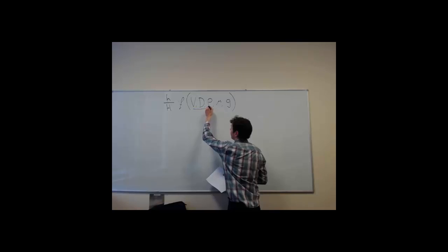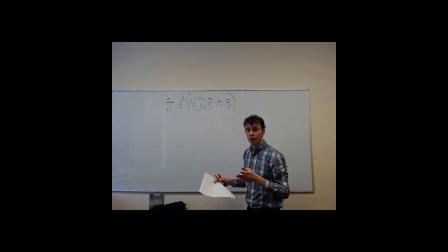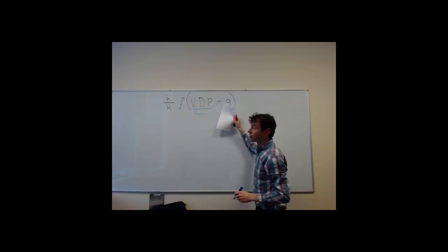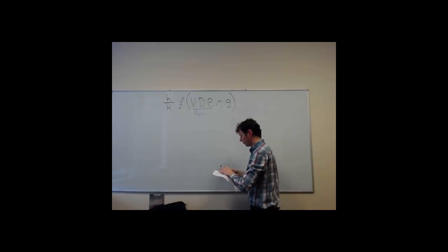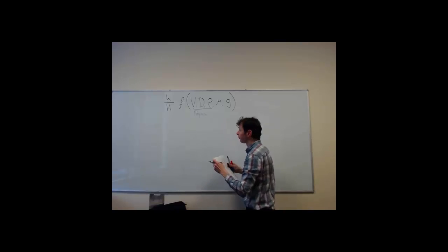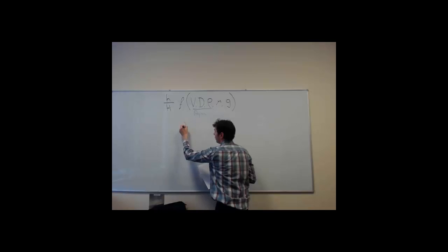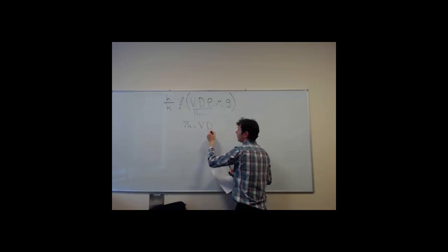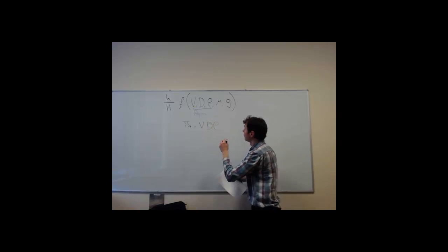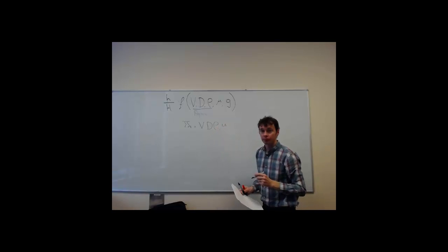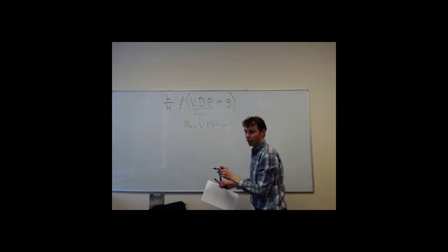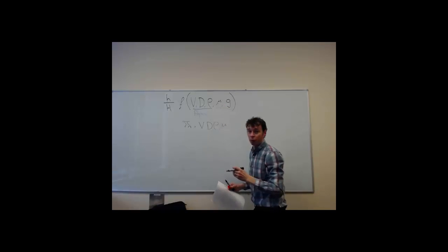So what we're going to do is velocity, diameter, and density, nice and easy to measure. They're going to repeat, which means that the dynamic viscosity and acceleration due to gravity are going to appear in one group each. Okay? So for our first pi group, pi 1 is going to be equal to velocity, diameter, density, and dynamic viscosity. The second pi group will be v, d, rho, and then acceleration due to gravity. So these variables only appear in one pi group only.